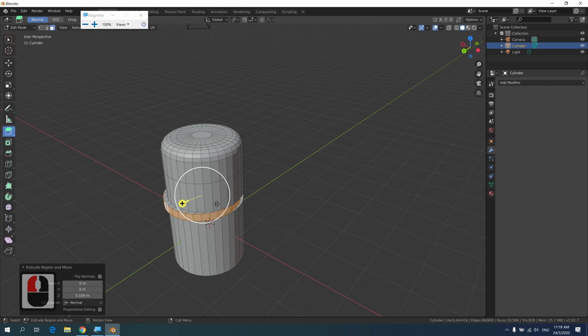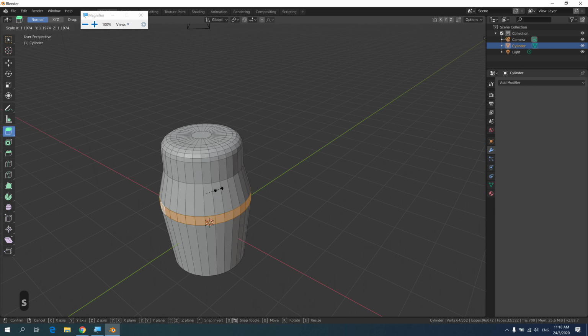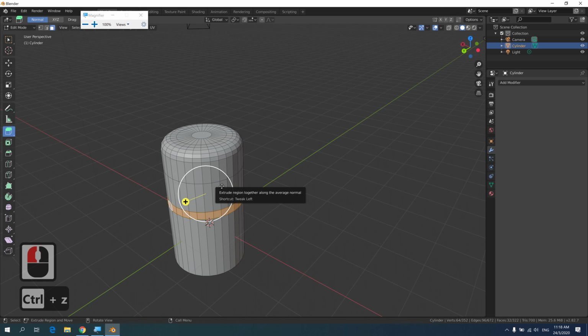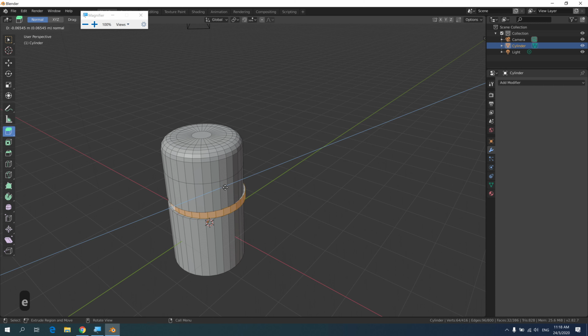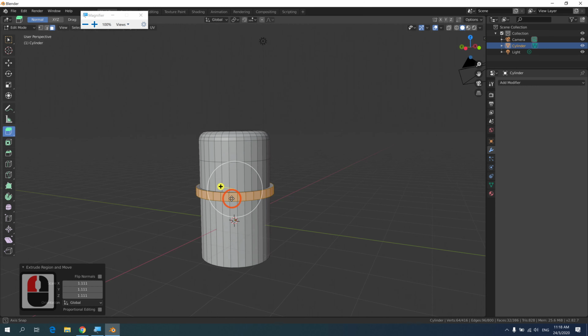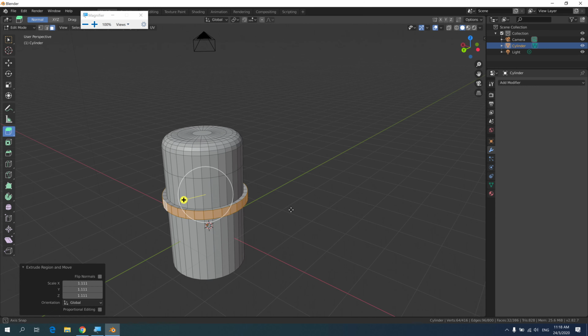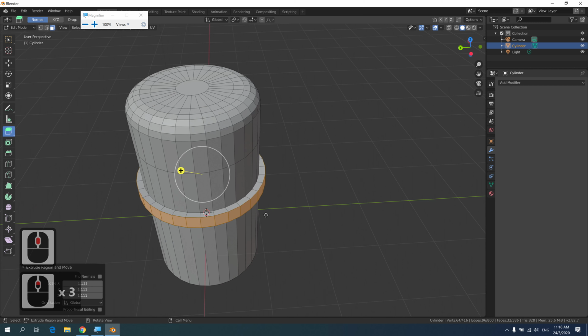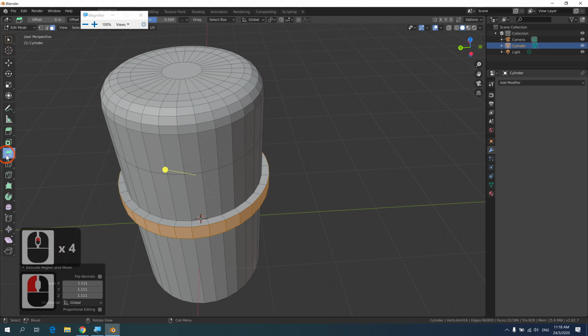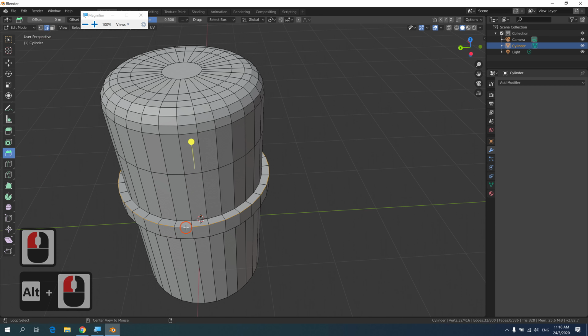For extruding this way, you can't really pull it; rather, what you want to do is scale it. Extrude once first, press E, and press S to scale. You kind of need to try and error and get the hang of how Blender works and what is used to do certain features. Likewise you can also bevel again, so we'll do a quick one.